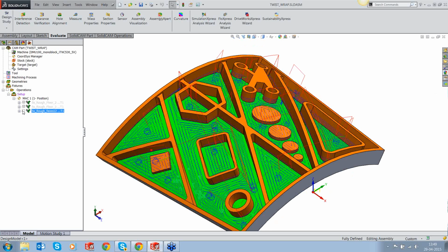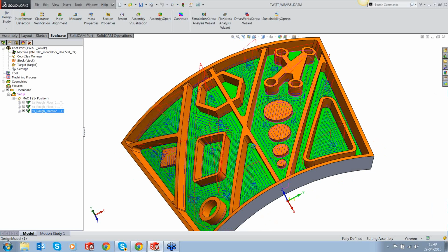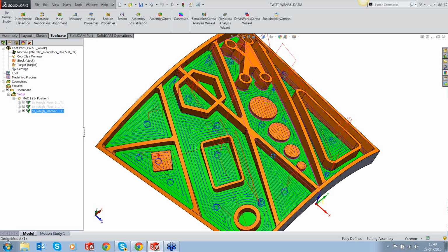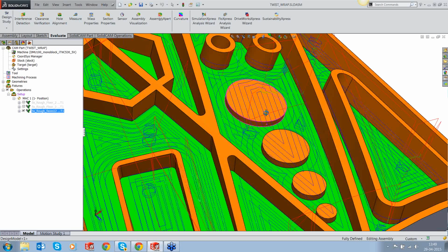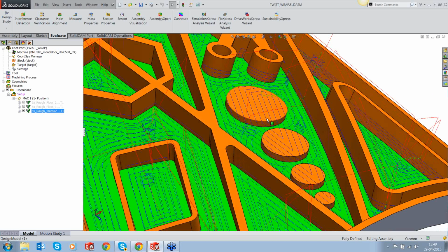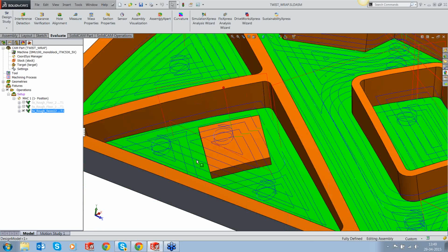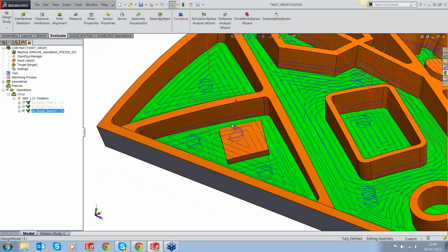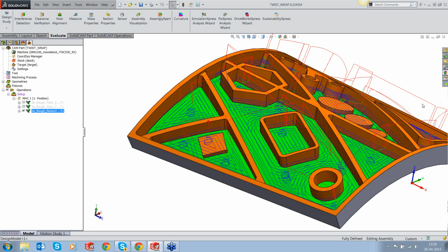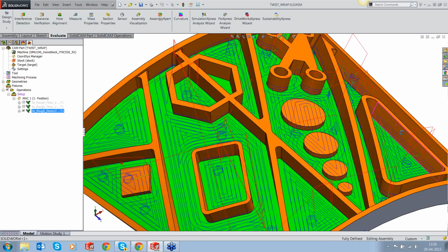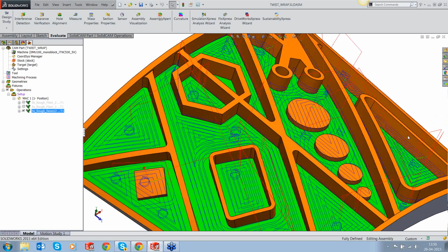That's it. You can look at the tool path. I said 2 passes, so you can see how the passes have been taken. Every place where it is doing an entry, I am getting ramping inside. It is ramping into the material. Some places, because we have used auto ramping or auto strategy, it's very difficult for it to provide helical ramping or different kind of ramping.